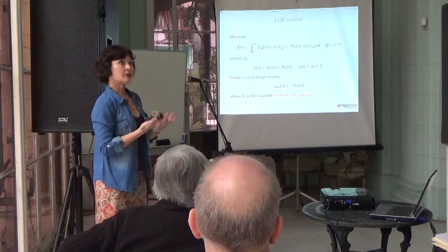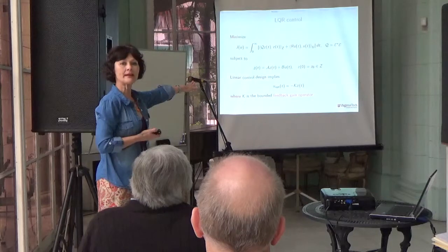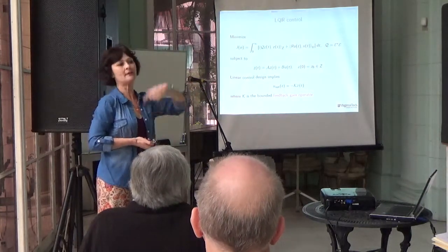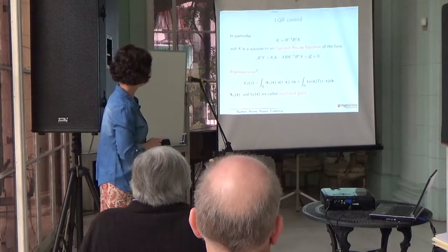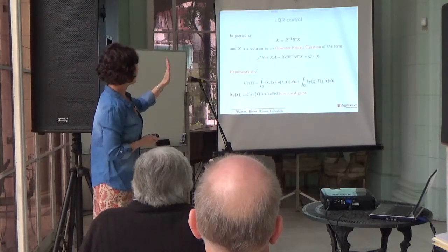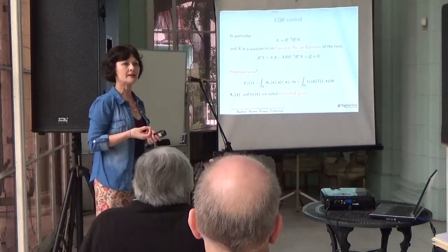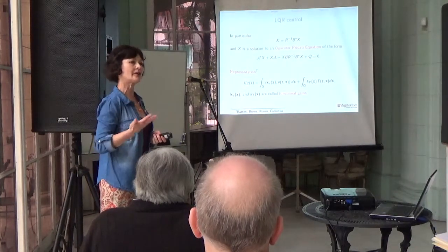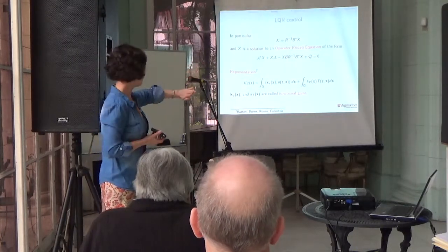So the things that one needs to calculate to design such a control system is one has to determine what that feedback gain operator K is, because if I have that and I have the state, I have my updated control and I can put it back in the system. So K is R inverse the adjoint of B times X, where X is the solution to an operator Riccati equation. It's a nonlinear equation, so you already get the sense that this is a hard equation to address. In this level, its operator is infinite dimensional.